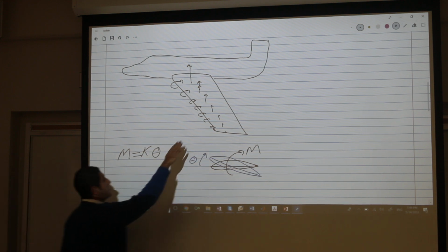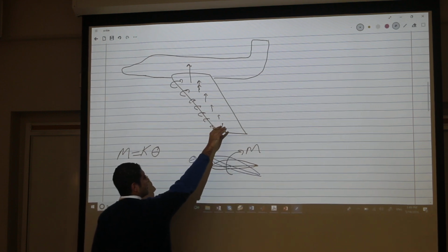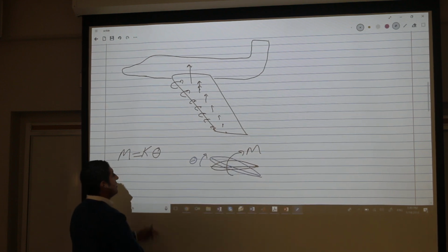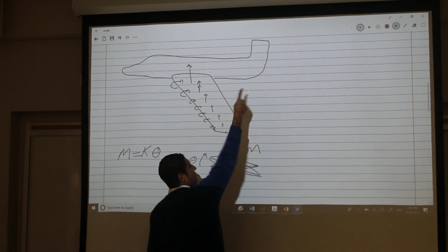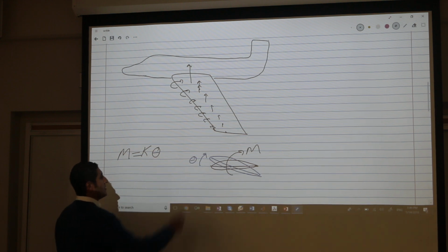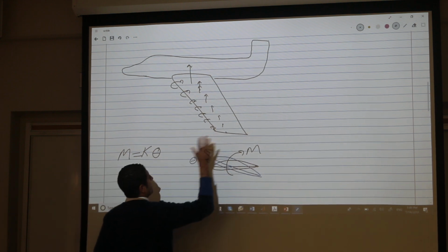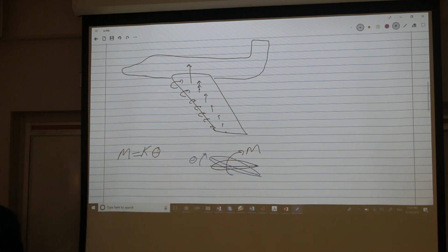So at the end of the day, at any two-dimensional section, there is lift and pitching moment at the aerodynamic center. The transfer of all these moments to the CG, in addition to the trim moment coming from the tail, must balance each other. But if you look at the wing on its own, it has a non-zero pitching moment. So this is the reason for having the tail: to balance the moment coming from the wing.